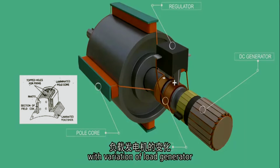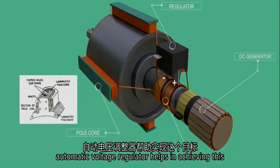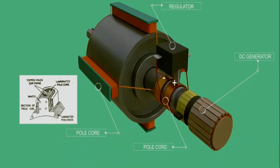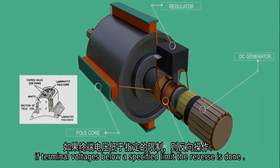With variation of load generator, terminal output voltage will vary. It is desired to keep the terminal voltage in a specified limit. Automatic voltage regulator helps in achieving this. Voltage regulation can be easily achieved by controlling the field current. If terminal voltage is below the desired limit, a regulator increases the field current. This will result with increase in terminal voltage. If terminal voltage is above the specified limit, the reverse is done.